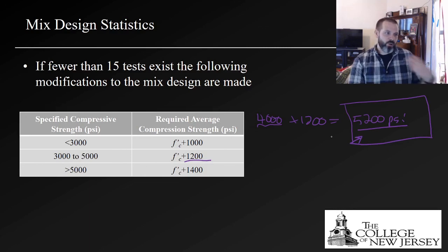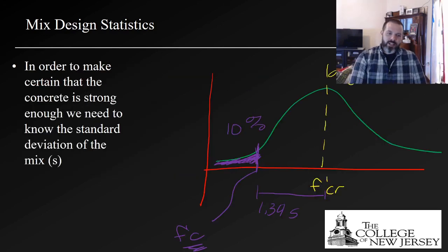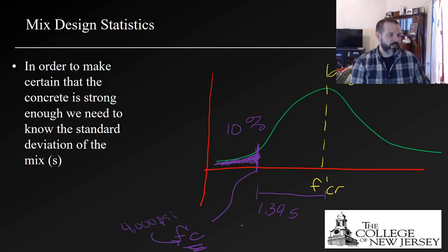So if you're an engineer and you ordered a 4,000 PSI concrete mix and you start testing and you get 4,000 PSI at your breaks, this needs to be a red flag in your mind, because if we zoom back, your design strength of 4,000 PSI is f'c. If you break a number of cylinders and this turns out to be your average, there's something wrong, right?